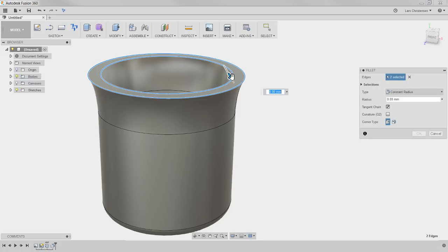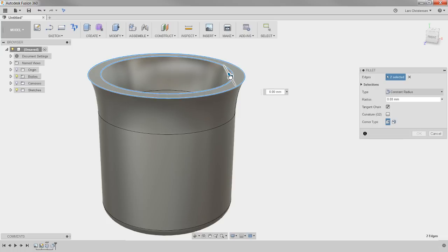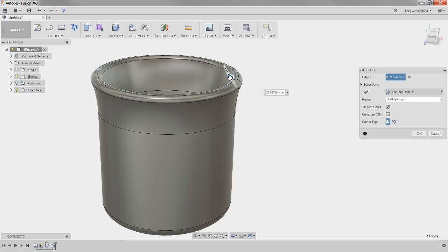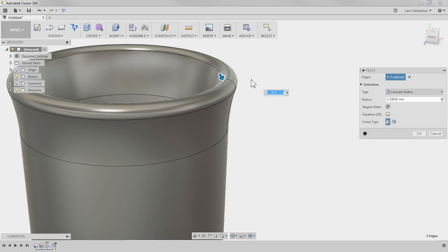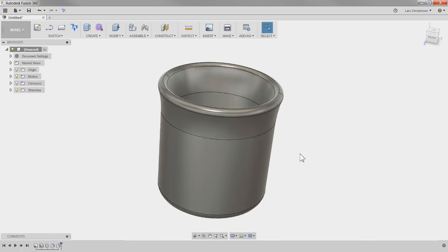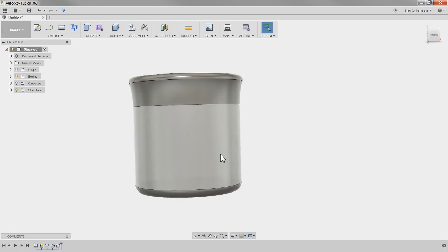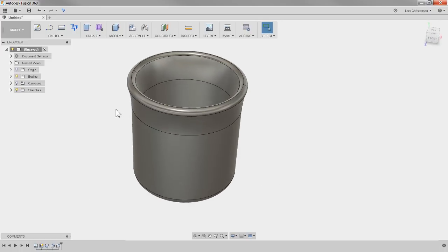I actually thought that the fillet tool would blow up if I went past 0, because this is 2 fillets. And I have some experience with other CAD software that I definitely know would not like when these 2 fillets kind of cross over one another, as it looks like they're doing right there. But it will actually do it right at that point. So bravo Fusion for that. I like that. Okay, so that starts looking more like the coffee cup.